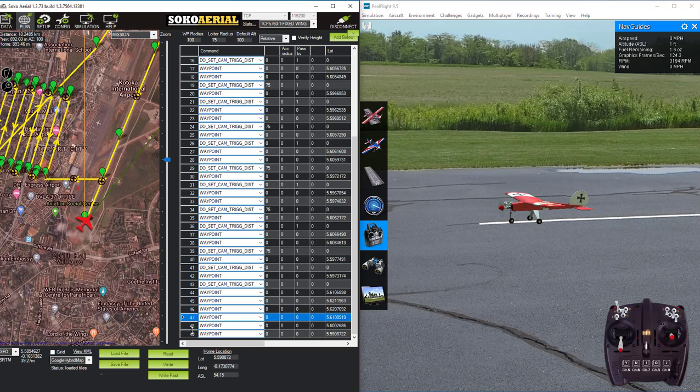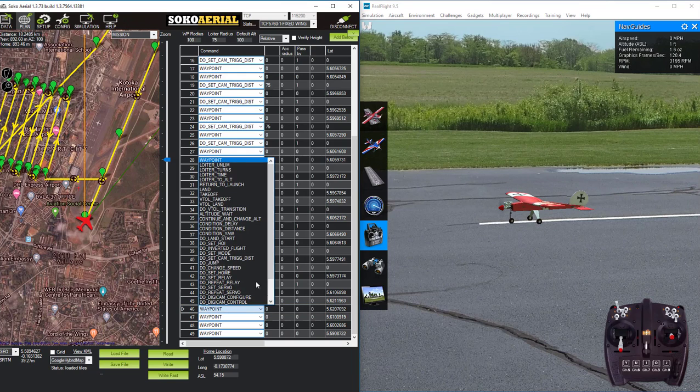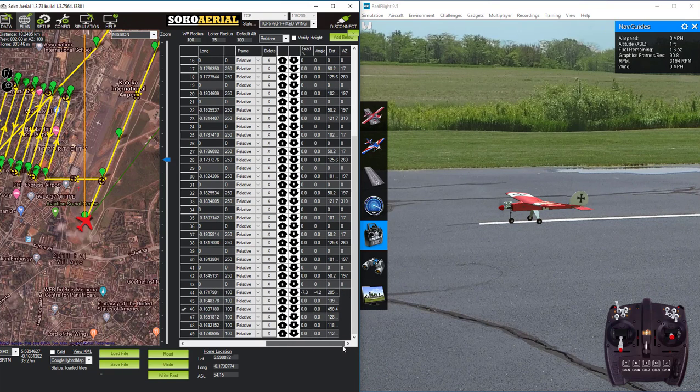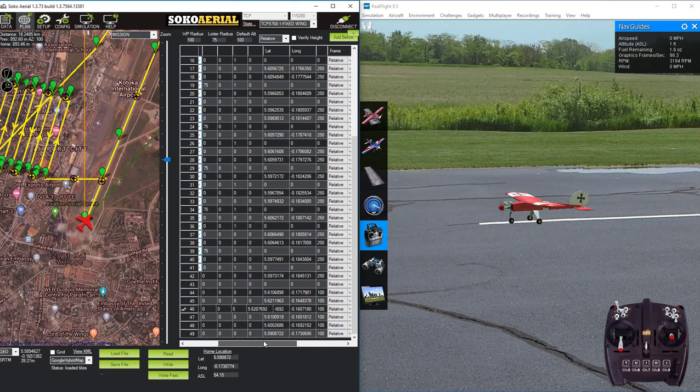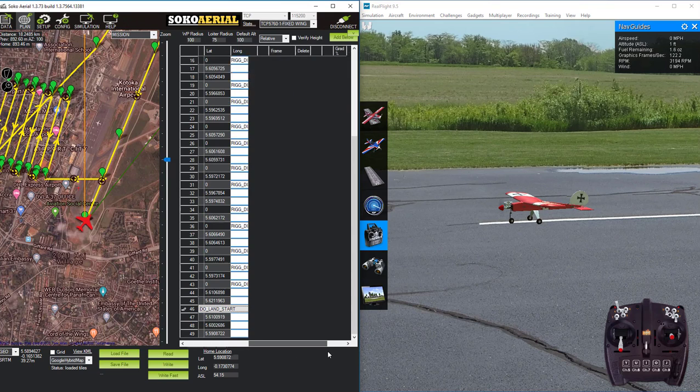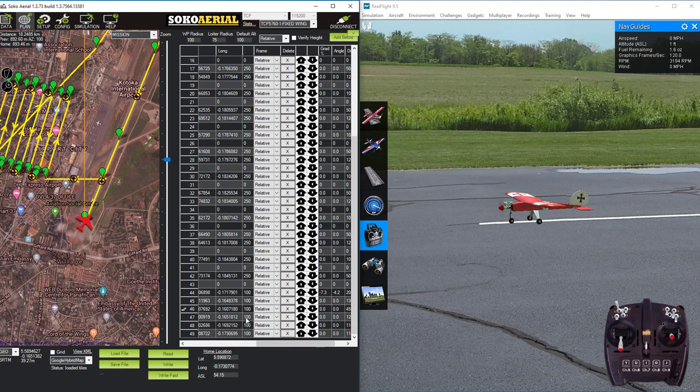is to focus on the four main landing approach stages. So I count from the bottom, 1 2 3 4, and then I initiate the landing sequence from the fourth stage. So that's I do land start, and then from there I start to reduce the flight height. So from 250 to 100, and then after the do land start, it drops to a very decent height. I don't want to change very abruptly and burn so much power.